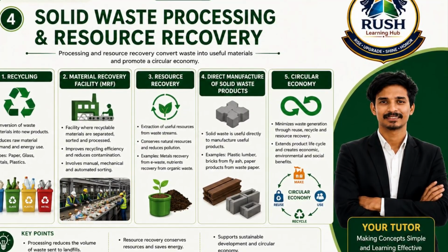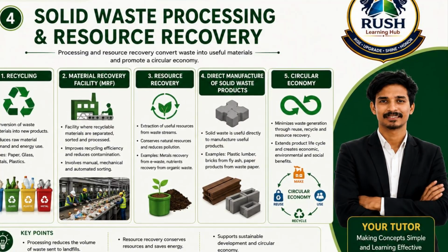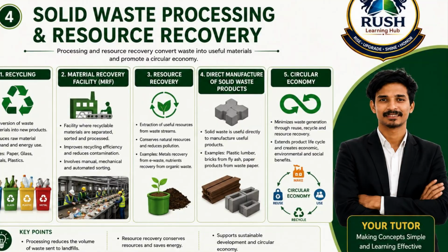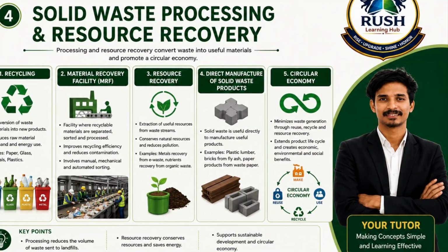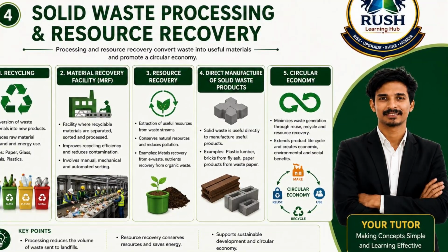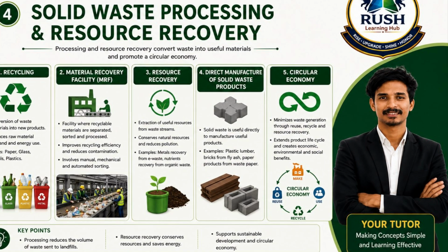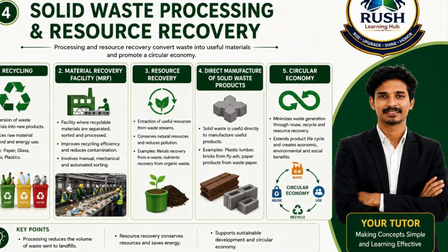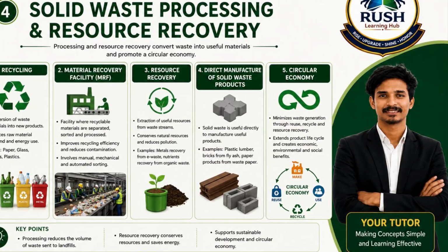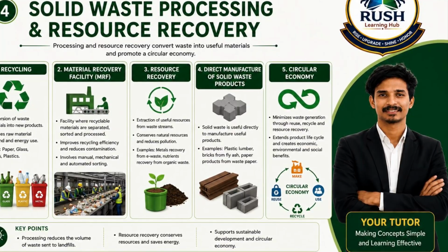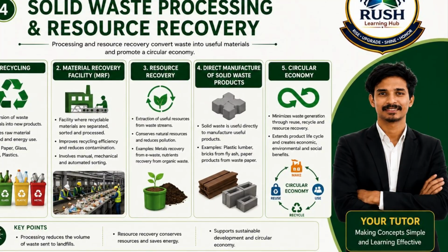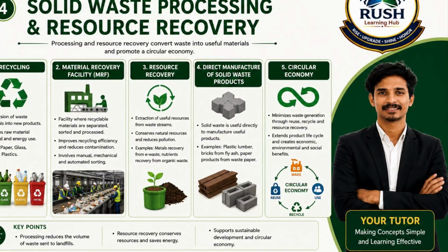Segregation means separating waste into different categories according to its physical and chemical characteristics. Segregation can be carried out in two ways. The first is source segregation, where households separate biodegradable waste, recyclable waste, and hazardous waste before collection. The second is centralized segregation, which takes place at treatment facilities after waste has been collected.